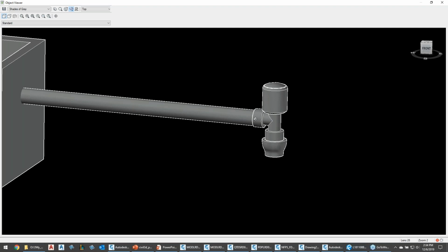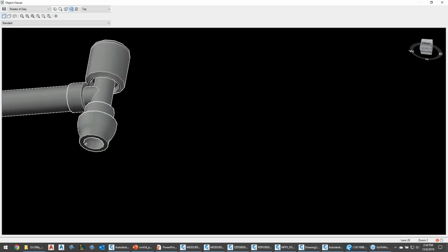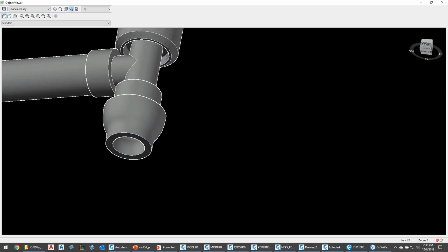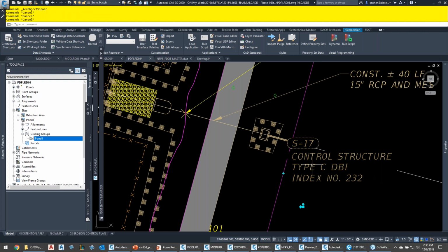I basically was able to kind of snap right here. So this pipe is actually a pipe. It's an actual pipe in there. And this right here is I just grabbed the center of it and snapped to the center of that. And I had this configuration of stuff. And I just messed around with the Scale 3D tool to make it scale to the size that I want it to be. There's my orifice. It actually is, believe it or not, at the actual scale that it's supposed to be. Again, a little overboard, but this is a true 3D model.